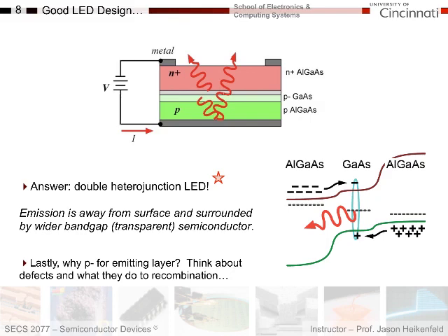Well, what is a bigger defect than taking a perfect semiconductor like gallium arsenide or some other semiconductor and putting dopant atoms in it? Dopant atoms are actually defects. They don't fit in the right size. They generate charge. They are actually defects if you think of it from a semiconductor standpoint. So typically for LEDs, your light emitting regions, you make them lightly doped because the dopant atoms themselves can act as recombination centers or defects to promote recombination that is non-radiative and which just generates heat.